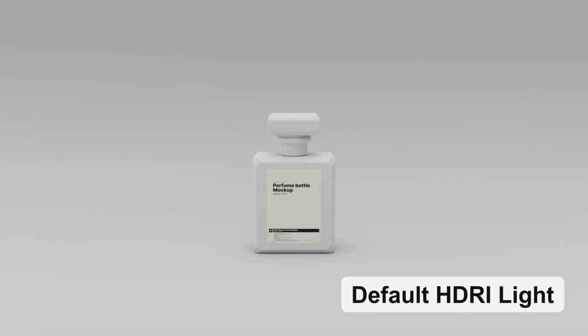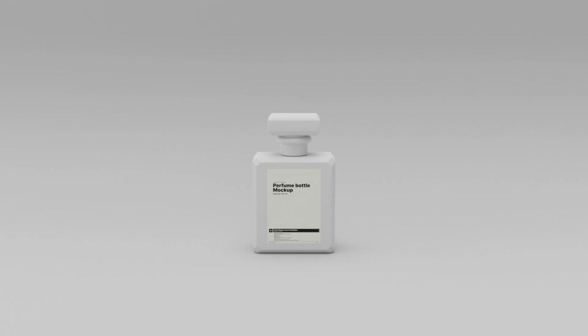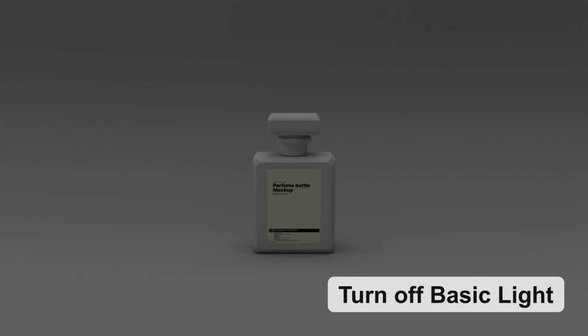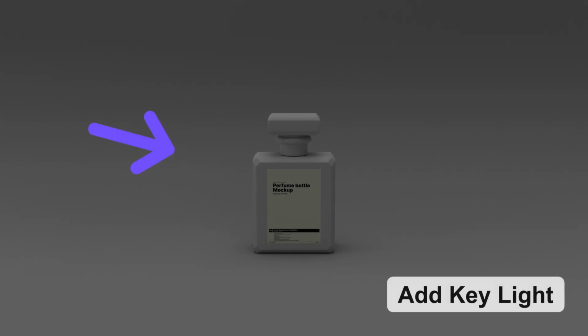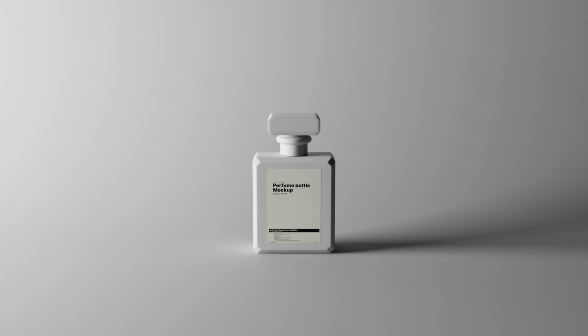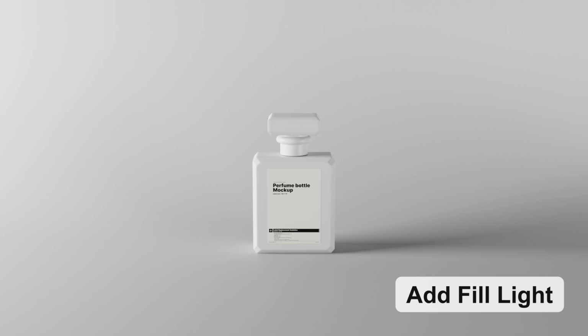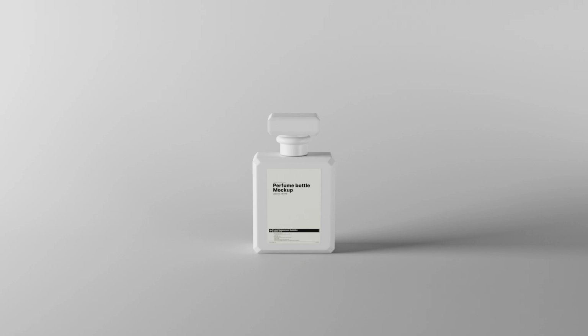While the default HDRI is great, let's explore the concept of widely used 3-point lighting setups, which allows for custom light configuration across various fields. First, place the key light at a diagonal angle from the front and center of the object. This is the main light that illuminates the product with the highest intensity. Second, place the fill light opposite the key light at a symmetrical angle. With about half the intensity of the key light, it softens the shadow created by the key light.